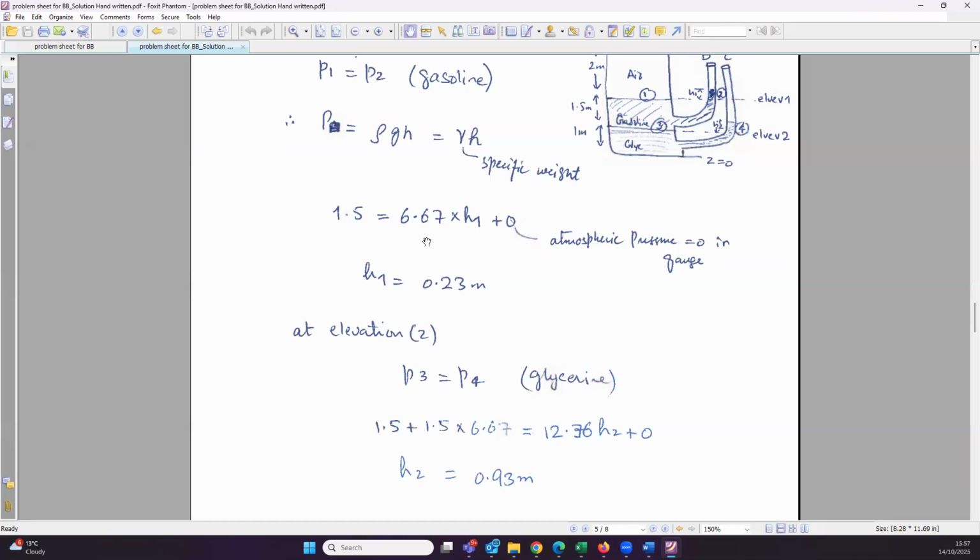So units will be the same because absolute pressure and gauge pressure have the same units. So they satisfied the equation in terms of units, but they totally forgot about the concept of absolute and gauge pressure. Just make sure that you are solving both sides in equivalent concepts and equivalent units, gauge pressure, and also you are taking the units into account.